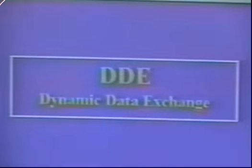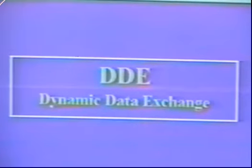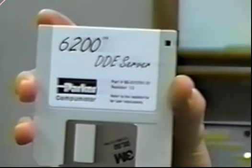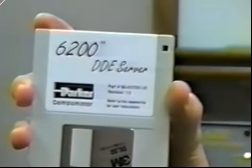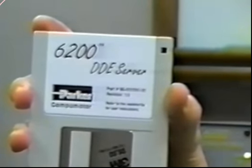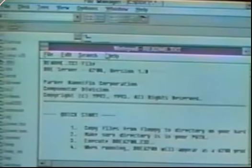In summary, let's review the steps to using DDE with Parker Compumotor's 6000 series products. First, make sure you have installed the correct DDE server that corresponds to your 6000 series motion controller. Second, review the readme.txt file on the DDE server disk. Third, verify that the DDE server is running and connected properly.